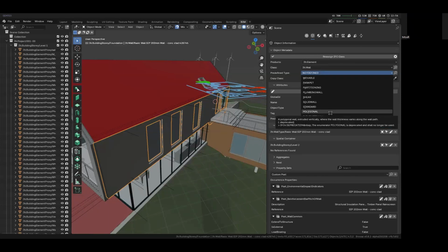Whereas polygonal will not have this constant thickness. It might change, and so the traditional wall detail, where you say here are the wall layers, off you go, Mr. Builder, doesn't quite work in that scenario. And then you have elemented walls, where instead of drawing a typical wall detail and a length of wall, you're literally drawing out every single element of the wall, down to the studs and the insulation and the cladding and so on. So these three were more to do with how you draw the shape of the wall rather than the function of the wall. So that's what the wall standard case was.